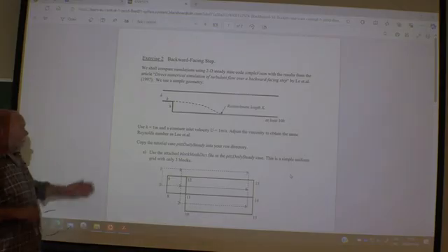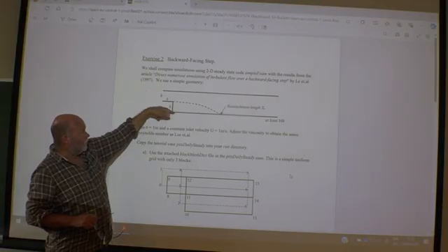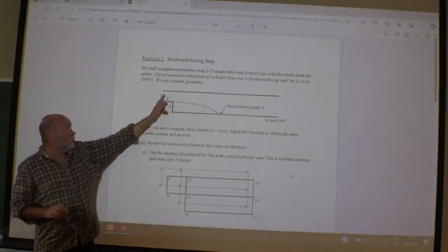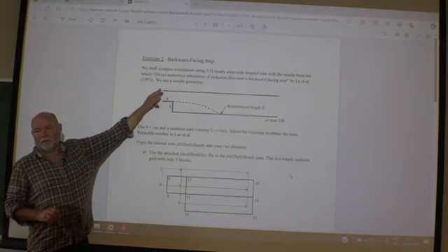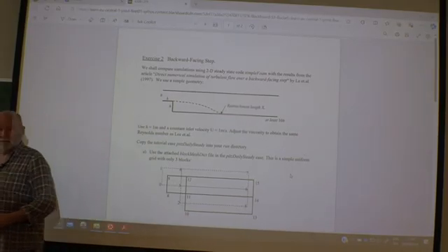For this problem here, turbulent flow, we have a symmetry plane and then a backward facing step. And here, initially, of course, you send in constant velocity, you give a constant k, constant omega, constant epsilon, which is probably wrong.